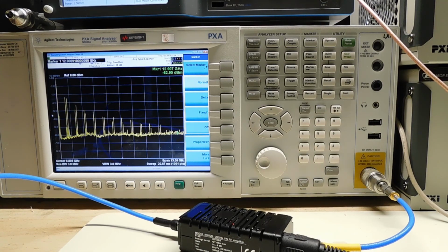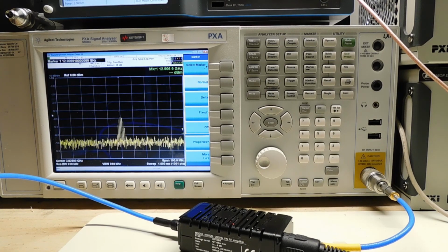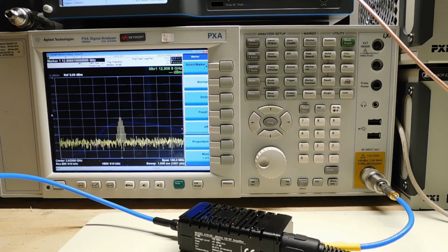One thing I can do is say, well, why don't we use it in the fourth Nyquist zone? So let me just tune it to 4 gigahertz, and you can see we have a faithful reproduction of the pulse. Now, what the Nyquist theory tells us, and how these things perform, is that the amplitude rolls off. The higher the Nyquist zone you get, the more amplitude roll off, and it usually follows a sin x over x function, as I've explained in different videos. So you can see the amplitude is quite low. Let's put the spectrum analyzer back in full span.